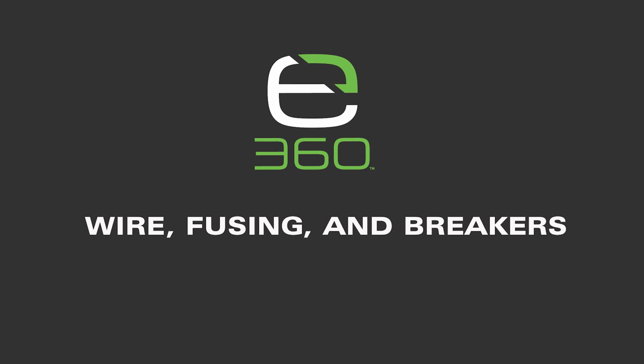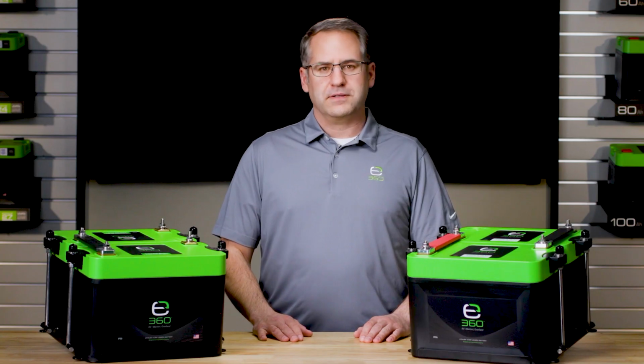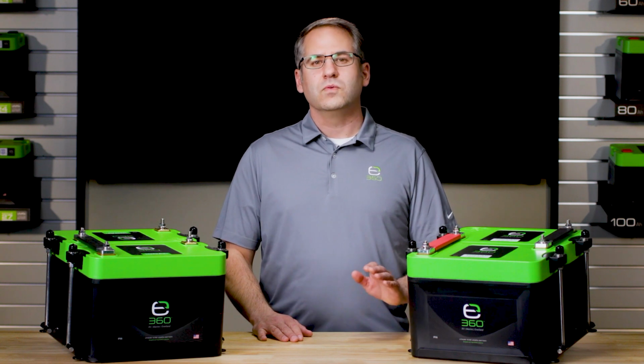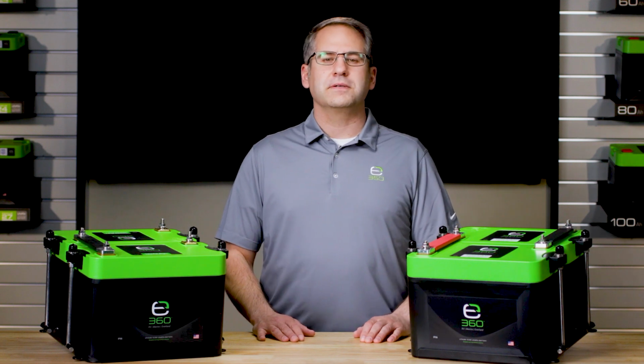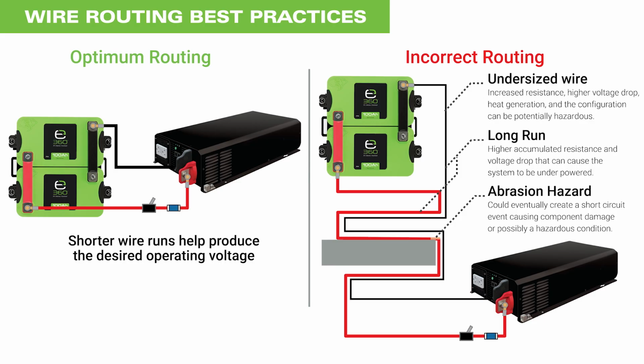Let's cover the topic of circuit protection when it is related to components such as wiring, fusing, and circuit breakers. When wiring, there are a number of factors to consider, such as routing or lengths, average wire gauge, conductor material, and voltage drop. When routing your wires, it is important to keep the lengths of every run as short as possible. It is also imperative that you avoid any potential abrasion or sharp objects that could cut or damage the wire insulation and cause a short circuit.